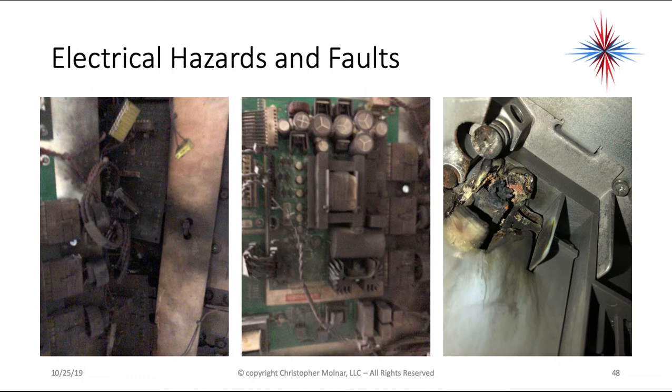Some high voltage and electrical hazards and faults can cause an arc flash. Okay, these two pictures over here are an example of an arc flash that happened within a VFD. This is an example of a surge that caused a meltdown of the connecting lugs for, it happened to be L3 on a VFD. So be very aware of the high voltages and what can happen. If this had been in someone's face without PPE, they would have probably been in the hospital or worse.